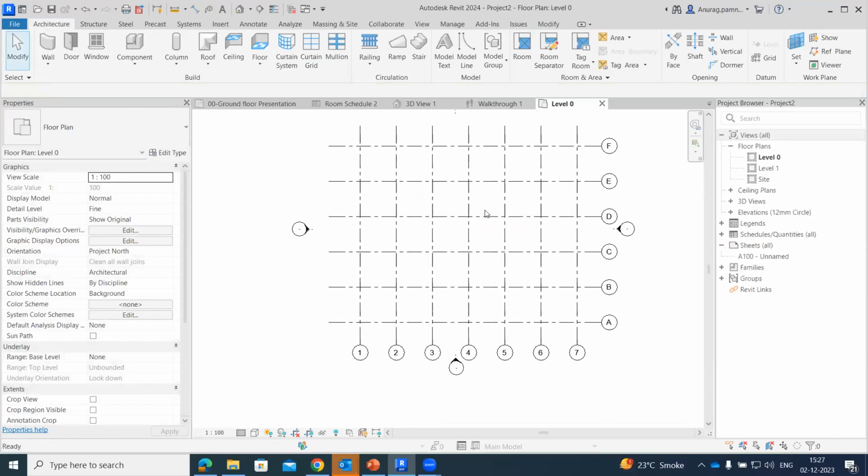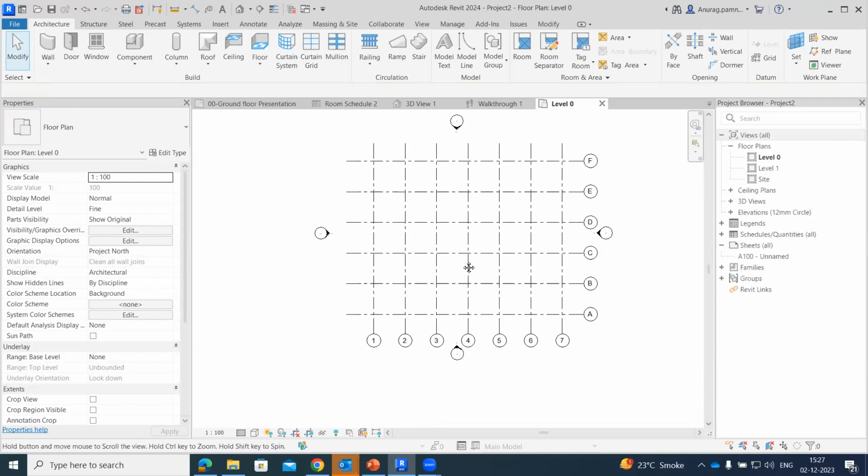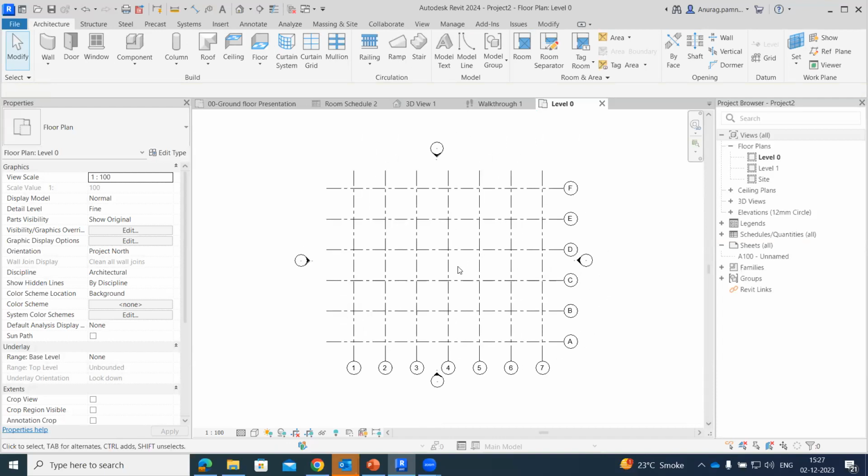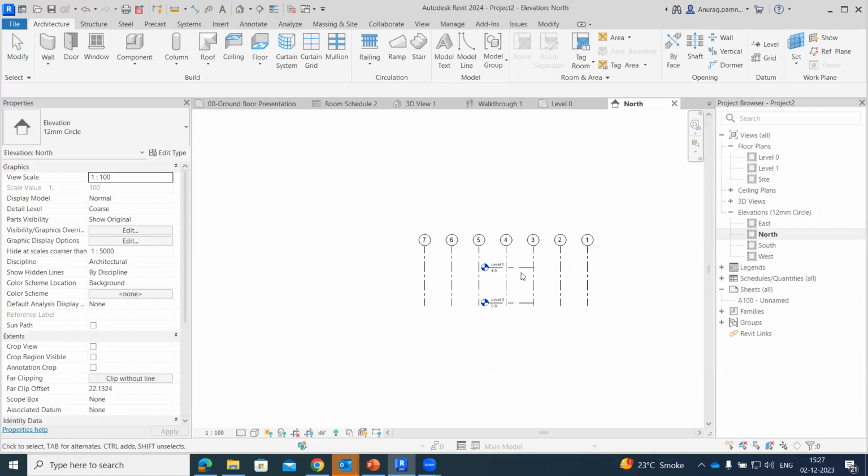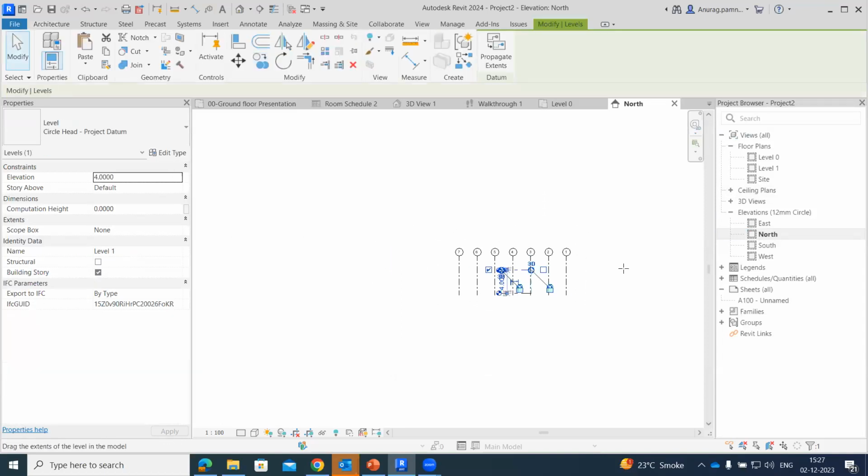And now what I would be doing is working particularly on the project levels. So I need to set the entire levels. If I'm going to associate a particular element to a particular plane, say wall, I have to give it a particular height to develop the volume of the wall. That can be done by moving on to the elevations. So here we have an elevation tab, and we can go on to any of the elevations. Just select it and drag it likewise.